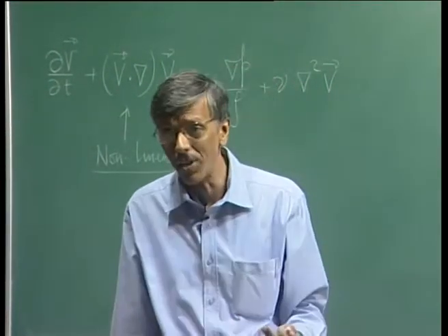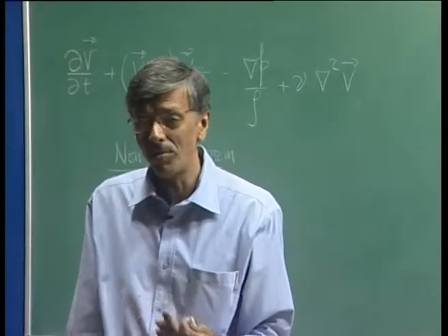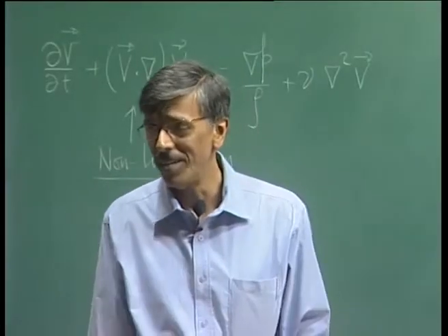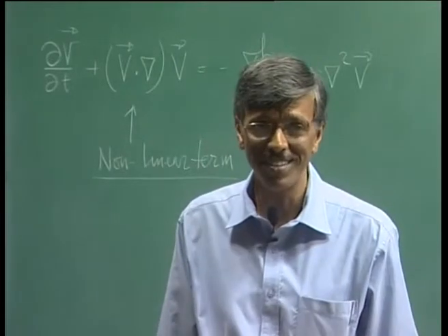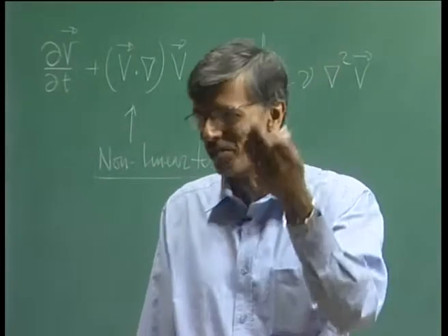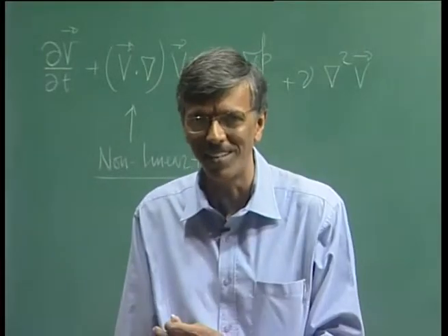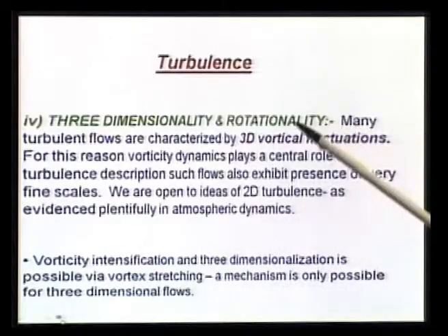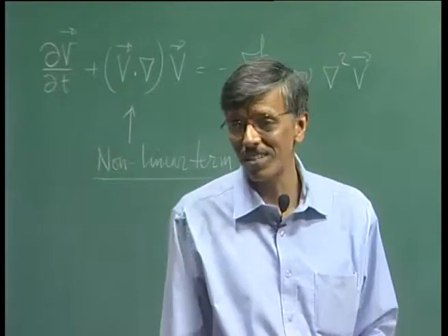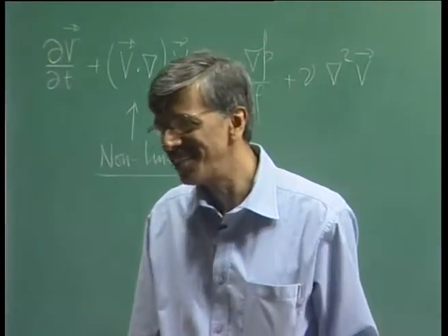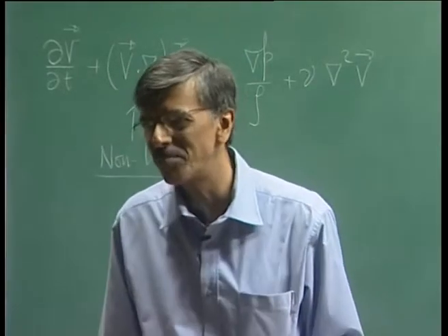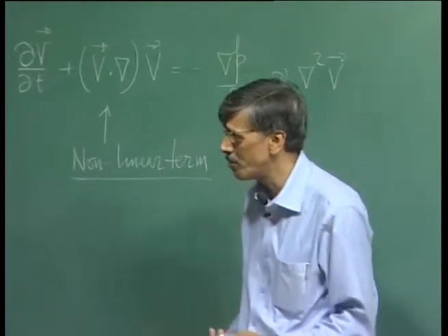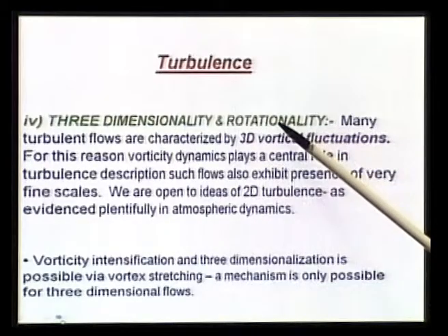Okay? So, we could do that. What I do is, if the flow is irrotational, that term will go away. So, what is the nonlinear term doing? Just simply redefining the pressure, that is, P by rho plus half v square. That is what you see, what we are talking about, the role of rotationality. So, if I do not have rotationality, nonlinearity does not do much. It just simply redefines the pressure. Okay? So, this is something that we need to understand, that rotationality is central in understanding turbulence.